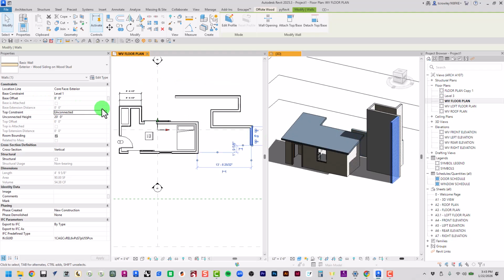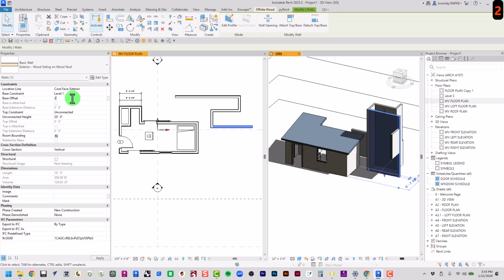Okay. If I were to select this wall, I could say start at level 1, but I'm going to give you a base offset, so you start 2 feet above level 1. And then I'll give you a top constraint of level 3, and we'll say I'll give you a negative top offset of -2. Wow, what does that mean, right? So now this wall starts at level 1, but 2 feet up above that. And it ends at level 3, but 2 feet below where level 3 is. So that's how you use those properties and those constraints and your levels.